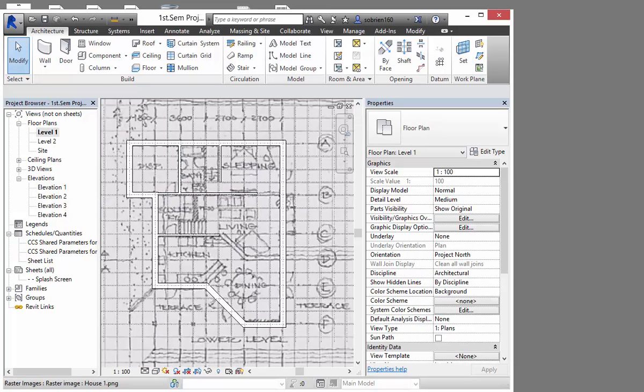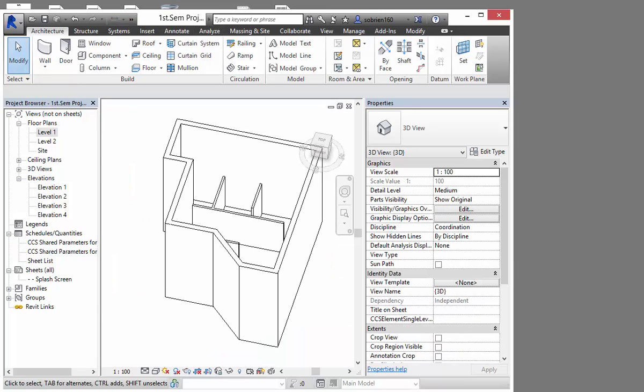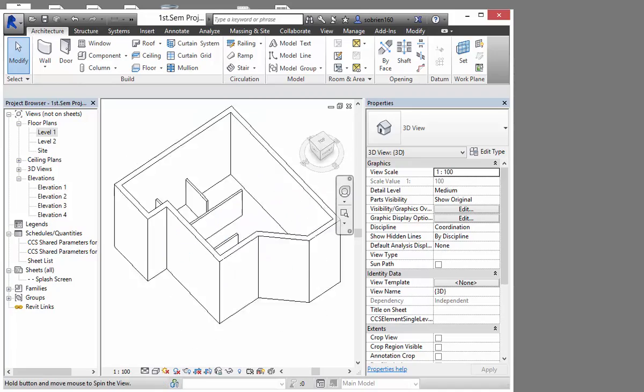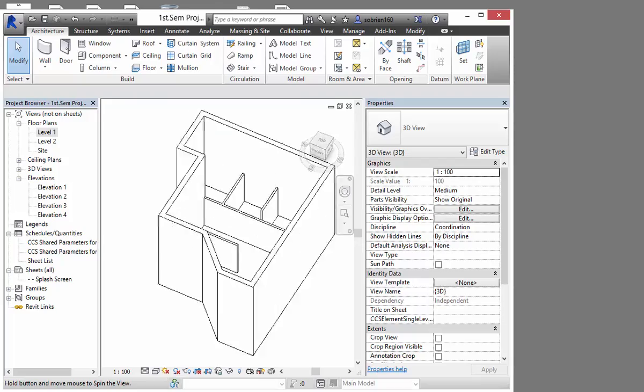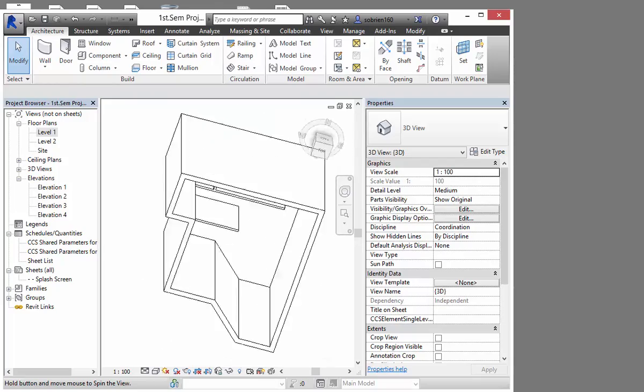How did you get your settings to like the orbit mode? Yeah, that's a shortcut. Sorry. If we go into 3D again, if I hold down the Shift key and I hold down the mouse button, you can just very quickly rotate the model around like that and have a look at it from all angles.